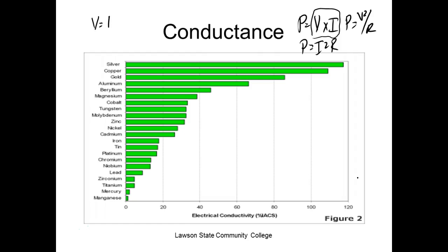So if you've got an outlet that's getting hot, or a wall switch that's getting hot, how much resistance should a wall switch have? Zero. You don't want it to produce power, right? You want it to control your circuit, but you don't want it to do electrical work. So if you've got a wall switch that's getting hot, what should you do? You should change it, because metals, when they get hot, oxidize faster. So you get hot, then your copper starts oxidizing, you add more R, you're trying to pull current through that thing, it gets hotter, and eventually, guys, you can get what we call a fire, right?